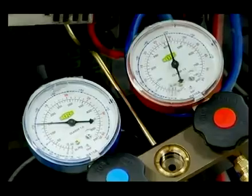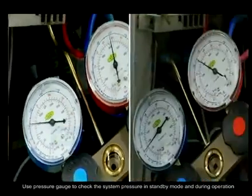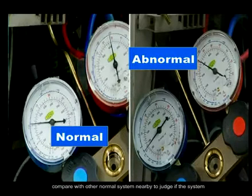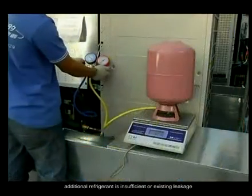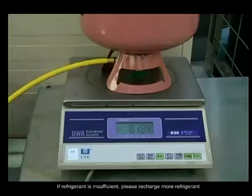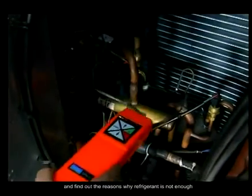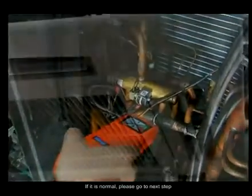Step 2. Use pressure gauge to check the system pressure in standby mode and during operation. Compare with other normal systems nearby to judge if the system's additional refrigerant is insufficient or there is leakage. If refrigerant is insufficient, please recharge more refrigerant and find out the reasons why refrigerant is not enough. If it is normal, please go to the next step.